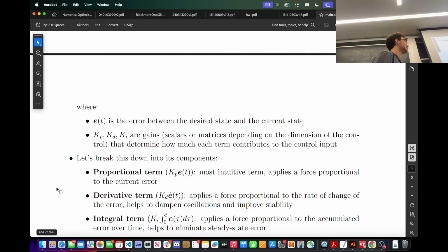this can lead to a phenomenon called integral windup, which is where you have essentially very large accumulation of error from the integral term, and then it'll make you basically go unstable, and it can do what you don't want it to do when you change the set point rapidly. Yeah. You set the integral bound low, so the integral gets larger really close to the target, so therefore it will not diminish. Yeah, you can do a bunch of things.